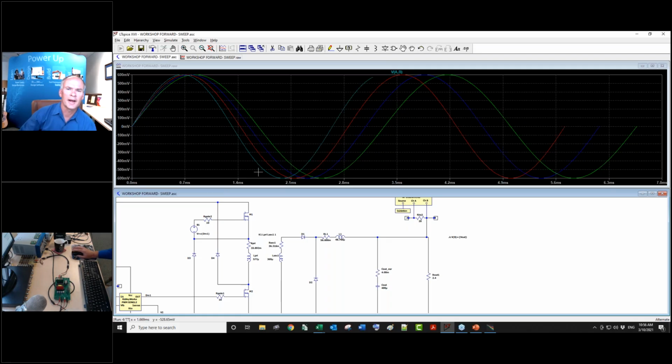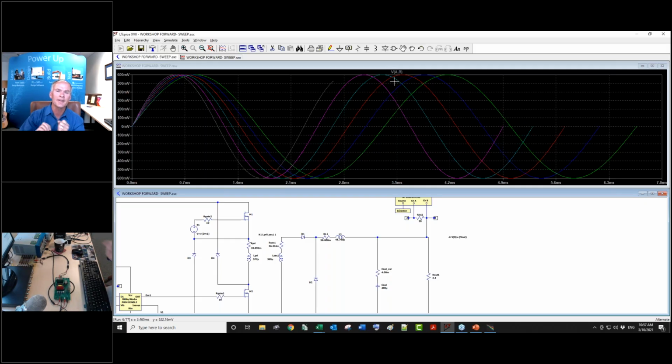Now, some of you will be saying, well, you should be using SIMPLIS or PSIM or something, but don't always be in such a hurry. Yeah, we could do this in PSIM or SIMPLIS in a few seconds, and then the result drops out, and it will be terrible. Sometimes it's good to just slow yourself down and watch it happen, because there's a lot to be learned here. We can see the injected signal, it's constant. This is what's breaking the loop.